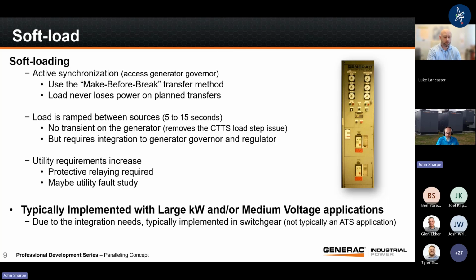Okay, we all understand this. I'm going over 100 milliseconds. So at this point, I'm in eternity when it comes to utility time, with electrical time. And at this point, absolutely, utilities are going to want to have a conversation about your utility protection. They're going to want some sort of protection to make sure that as these two sources are tied together and we're shifting load from one to the other in a smooth, soft load transition, we're not pushing back on the utility. The big thing they ask for now is some sort of multifunction relay that's going to protect the utility.